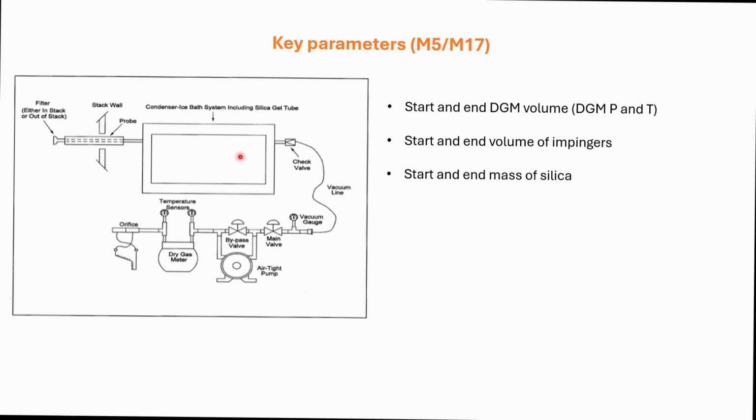And then lastly, you will record the mass of your silica gel before and after the test, because that difference in mass will be the mass of water that is absorbed by your silica gel.